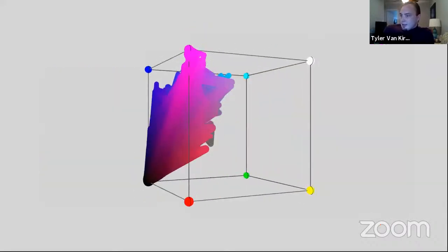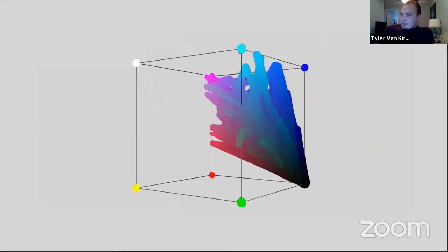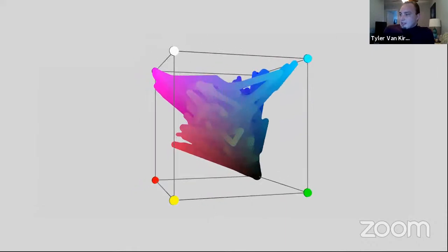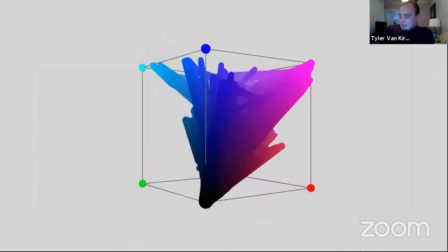So looking at it as a small resolution image, but using a Grasshopper plugin called Cocoon, which aligns small cubes assigned to these curves at different charges, and then wraps these cubes in a new mesh, it formulates this solid mass of these networks as a solid form. And by using the vertices of this new mesh in this color gizmo space and applying that to colorize the mesh, you would get something like this.